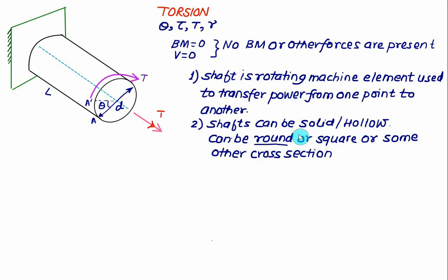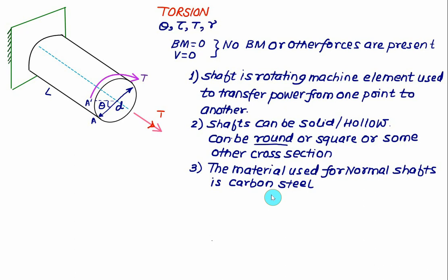Normally the solid shaft is used to transmit the power for a shorter distance, and if the distance increases, naturally the cost involved will be higher. The hollow shaft is normally the propeller shaft, which is used in the case of trucks or heavy transmission systems. Propeller is a hollow shaft. For normal shafts, we normally use carbon steel, and for high strength, nickel chromium alloy can also be used. Shafts are manufactured either by hot rolling, by machining, or by cold rolling and drawing.